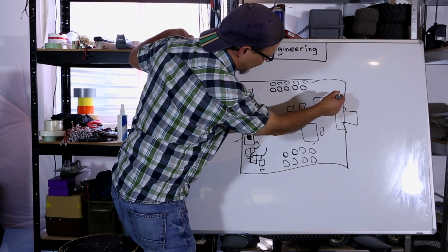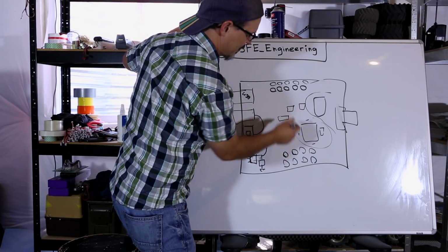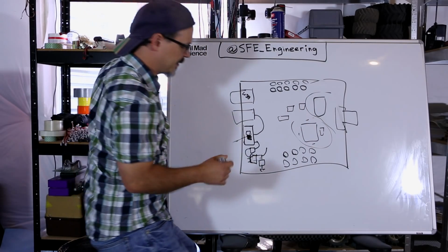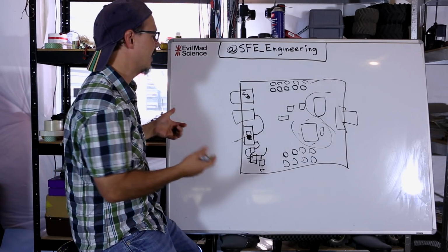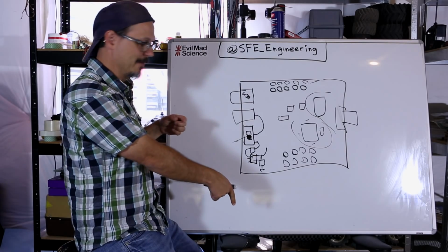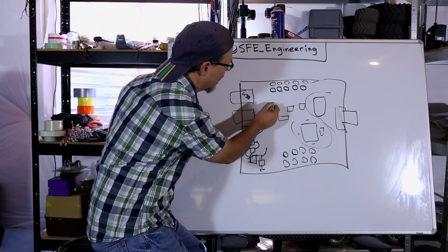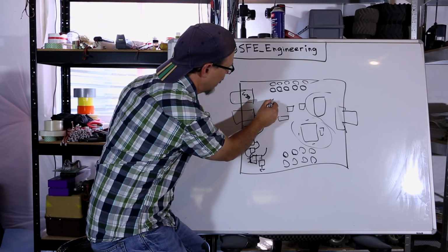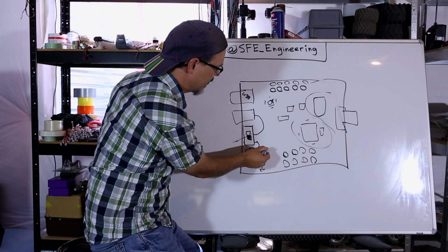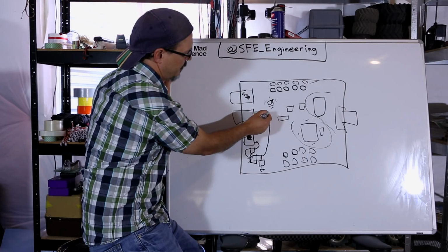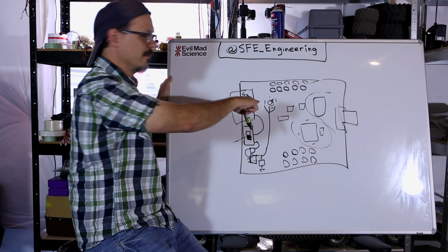But your sections, right, this is going to be your RF section. This is going to be your microcontroller section. This is going to be the sensor section. And the way you want to feed these things is by section on the schematic, right? So for example, if I've got an op amp here, there are a few different places I want VCC. Let's say I've got an op-amp section here, and a couple other components, and those things are strung out. What I'm going to do is run a single trunk line to this point, and then it's going to diverge to the different parts in the circuit where VCC has to be, right?